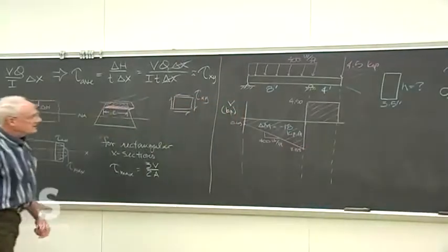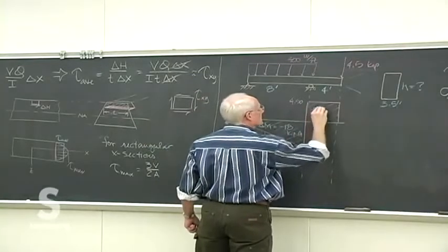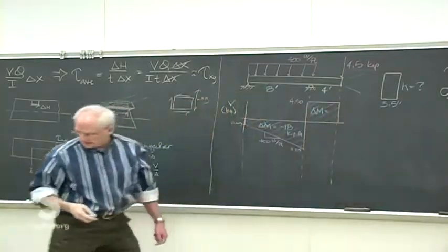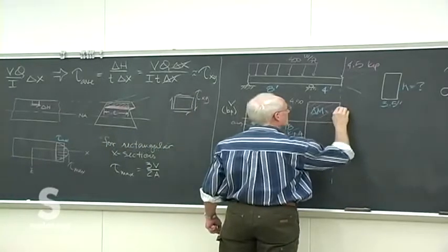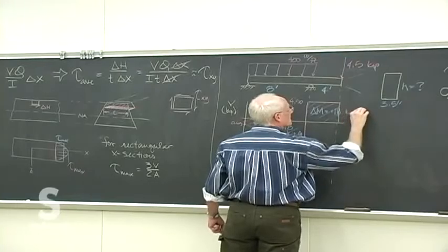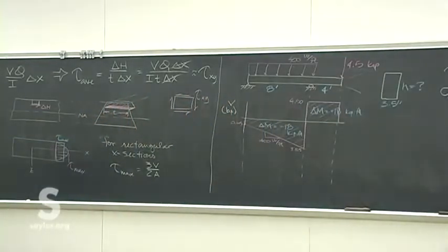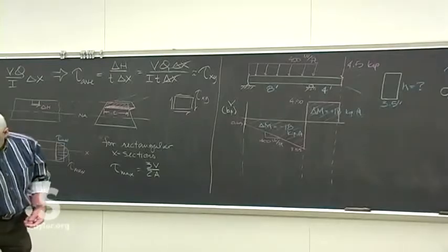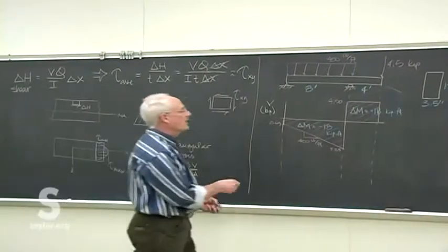That area turns out to be -18, and this area turns out to be +18 because it comes to 0. So we know that our maximum moment is 18 and it's right at the roller. Exactly what the shape of the moment curve is on either side isn't really of concern here, because what we need is to make sure that the beam resists the maximum moment,